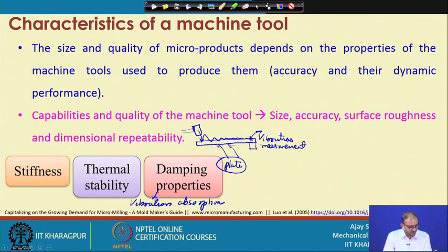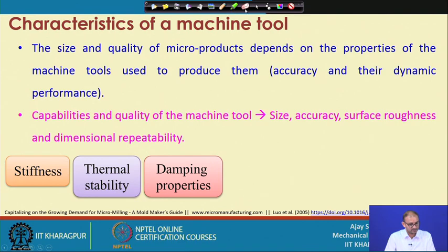So, if you are hitting very hard and this particular thing has a very low damping coefficient, then there is a problem of propagation. All the vibration will propagate and reach this location and it will continue for a little bit longer time also. So, what do we need? We need the damping properties to be very high in this case, so that all the vibration will be absorbed within the material only and it will not reach the joint. If it is reaching that joint, after some time the joint will become a little bit loose and then it creates a problem in the other assembly parts.